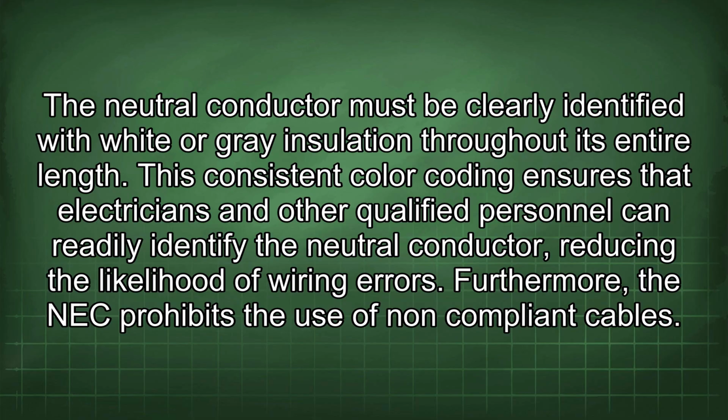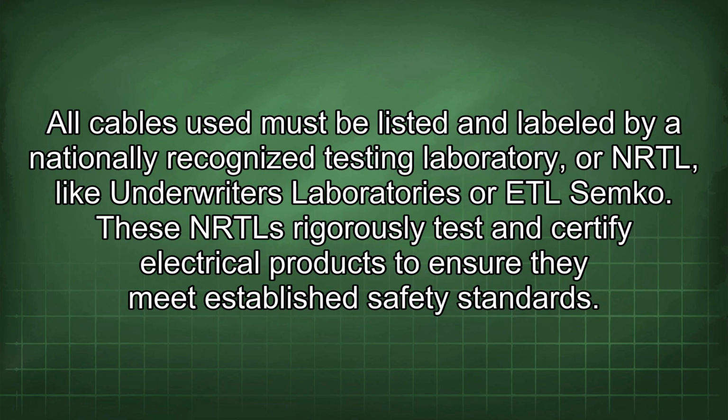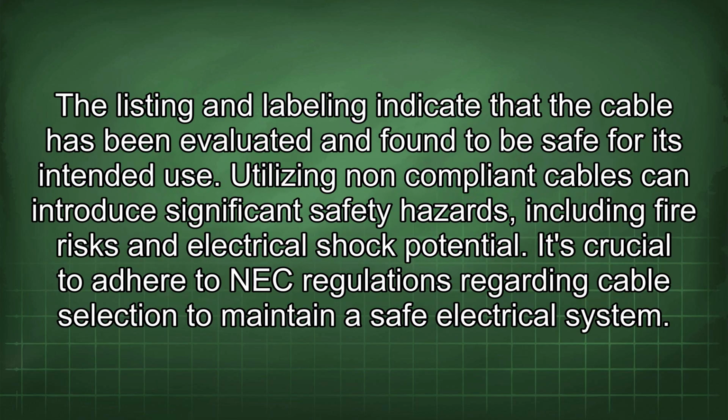This consistent color coding ensures that electricians and other qualified personnel can readily identify the neutral conductor, reducing the likelihood of wiring errors. Furthermore, the NEC prohibits the use of non-compliant cables. All cables used must be listed and labeled by a nationally recognized testing laboratory, or NRTL, like Underwriters Laboratories or ETL Semko. These NRTLs rigorously test and certify electrical products to ensure they meet established safety standards. The listing and labeling indicate that the cable has been evaluated and found to be safe for its intended use.